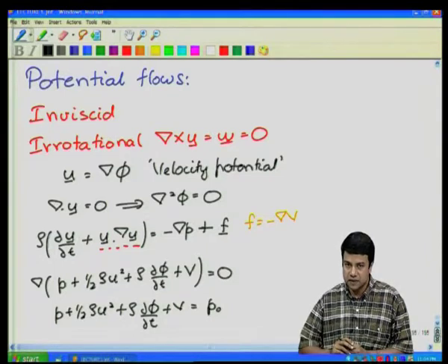When we neglected the viscous terms, we basically get a first order equation in the velocity or a second order equation in the potential. In the original equations, we could satisfy both tangential and normal velocity or stress conditions. In the modified equations, we can only satisfy the normal velocity and normal stress conditions.